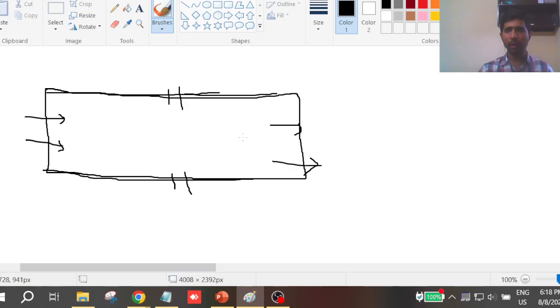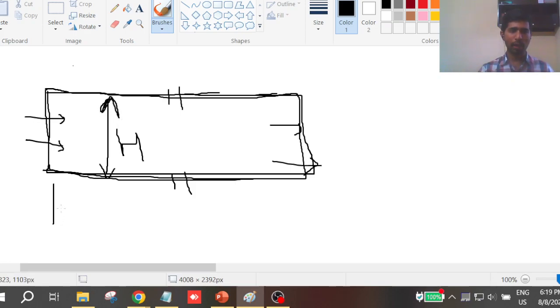But a major thing which you have to think about is the height of the channel. You know the height of the channel, but when you are selecting a computational domain, which means the area in which you want to finally get the flow variables and the temperature, say velocities and pressures, in which region do you have to get them? Say I select some rectangular region like this. I already know the height of this, but what length do I have to take, okay.